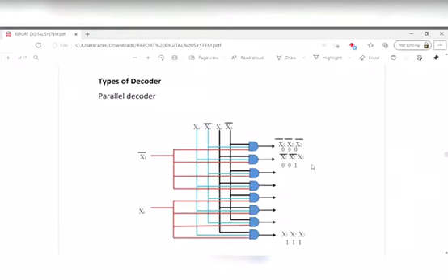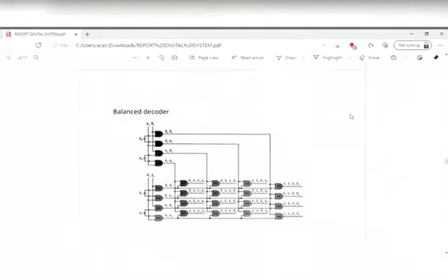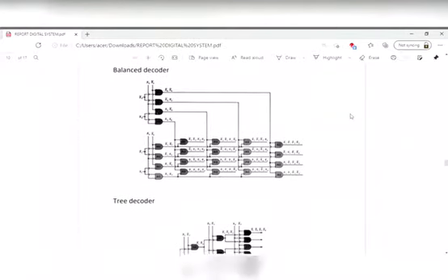The parallel decoder network has the advantage of being the fastest and most regular in construction of the three types. In tree network decoders, there are 4 flip-flops and so 2^4, which is 16, output lines, and examination will show that 56 diodes are required to build it.